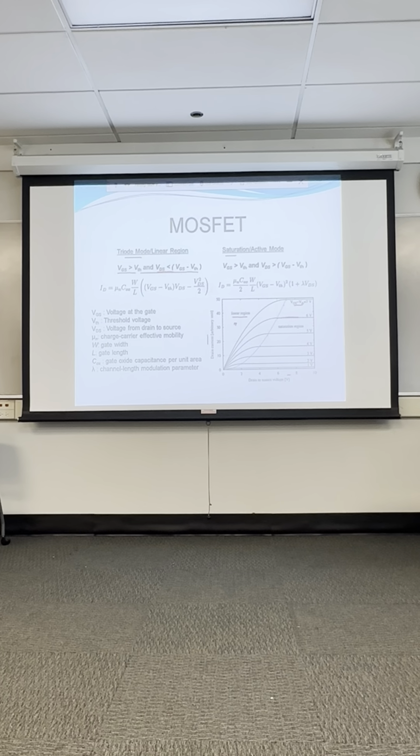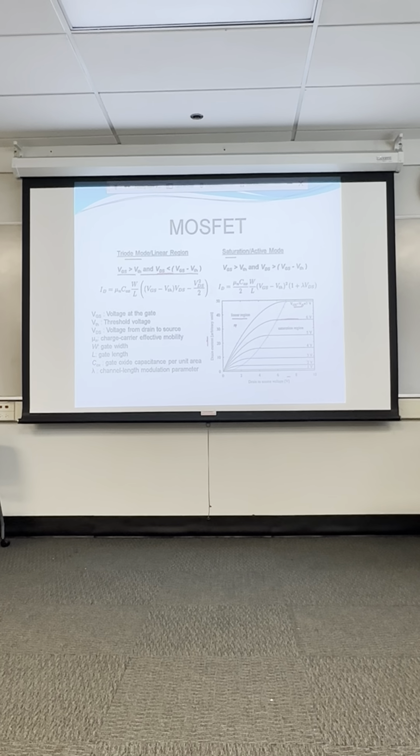If we want to increase the drain current upwards, we increase the gate to source voltage. So with this, the design here went from 1 volt gate to source minus the threshold up to 7 volts. And then we kept increasing the drain to source voltage. The MOSFET goes into saturation.